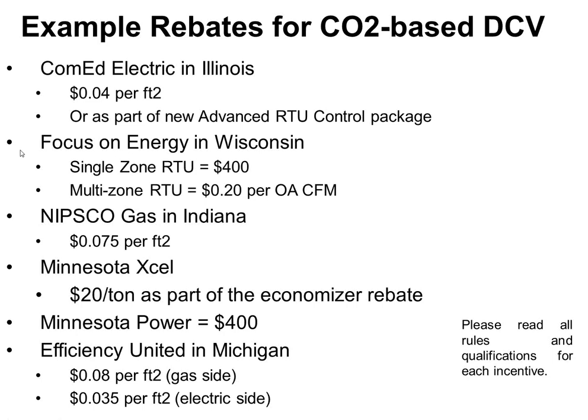On a single zone, we simply wire the CO2 sensor to the economizer controller that has an input waiting for it, and we set two different minimums, one for CO2 mode, which is basically what takes care of my square footage portion, and then one for square footage and people, which really becomes my maximum, right? And that's really straightforward and easy to do.